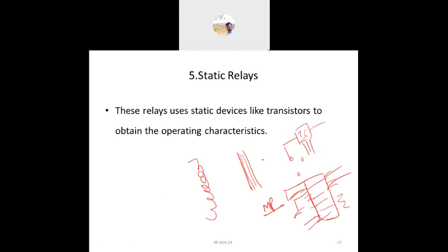So these are microprocessor based relays. In static relays there is only an electronic circuit combined with transistors. Based upon the input signal, it operates because of the comparator. It works on the basis of the comparator, by comparing the input signal and the output signal.